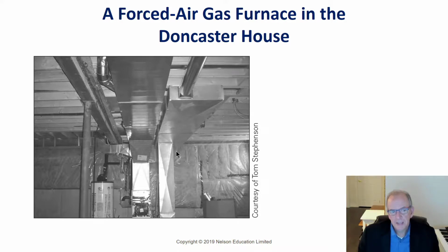The reason I say that is in Canada, we deal with very cold temperatures and we deal with very warm temperatures, at least in a lot of the locations. So if you use, say, a hot water heating system, then what are you going to do in the summer when you want to air condition the place? Then you've got to put ducts in anyways. So rather than put a separate system for hot water and a separate system for air conditioning, you use one system, and the duct system supplies and returns cold air or warm air, depending on whether it's summer or winter.